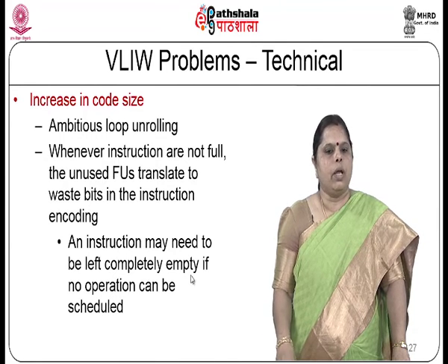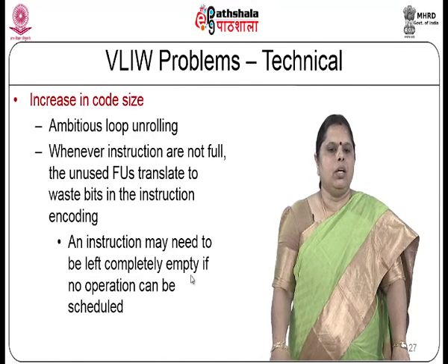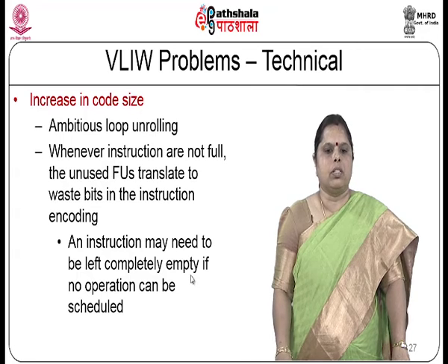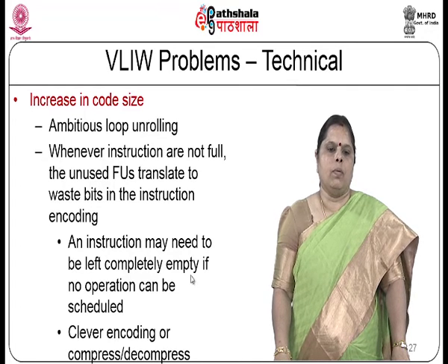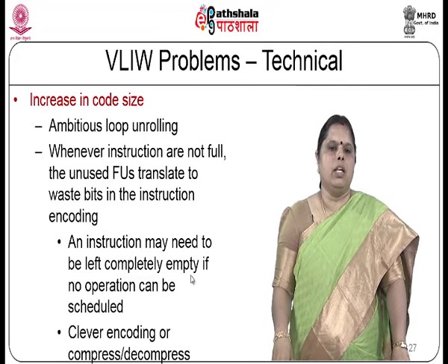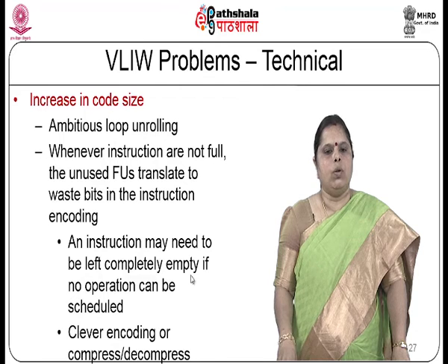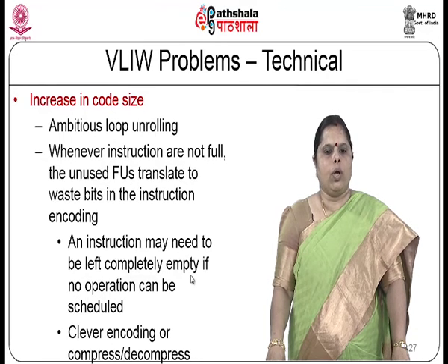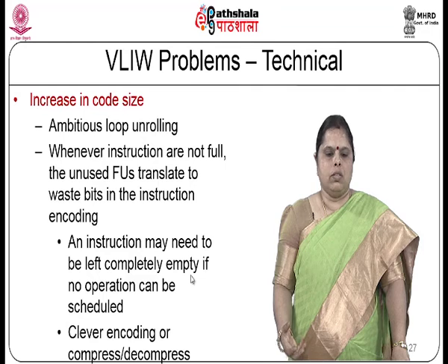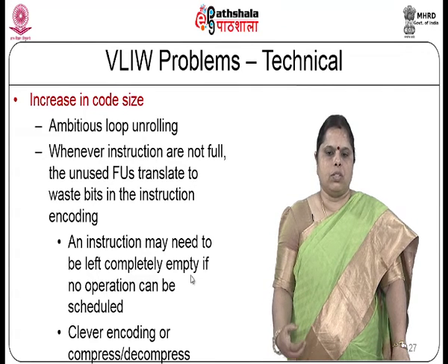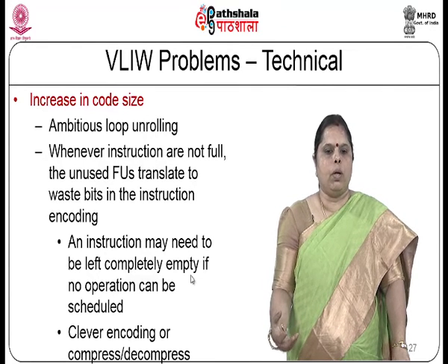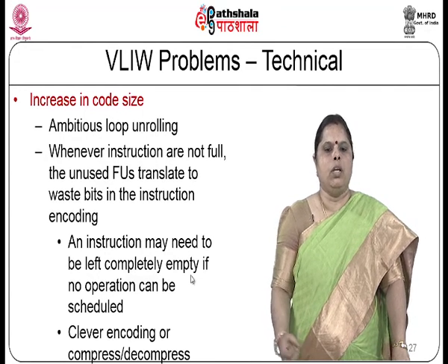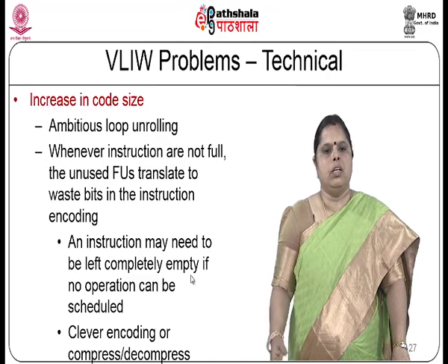An instruction may be left completely empty if you are not able to find any operation to be scheduled in that bundle. In order to avoid this increase in code size, people have looked at different compression and decompression techniques, where you can encode your instruction format and store it in a compressed form, and after it has been fetched from memory, you can expand it, decompress it and use it.